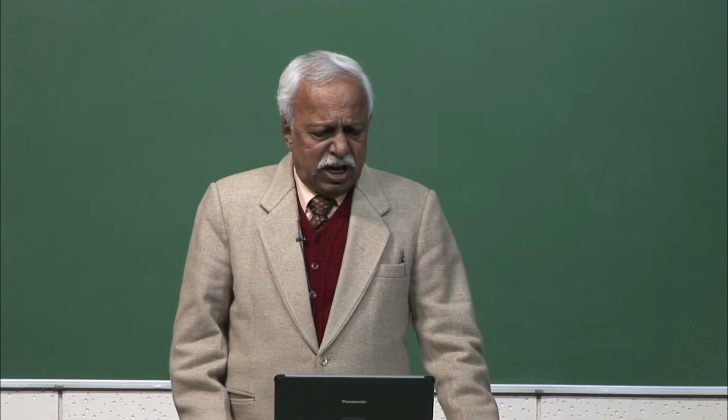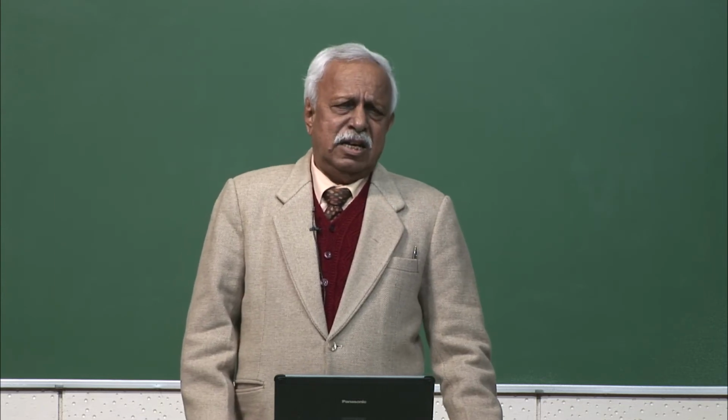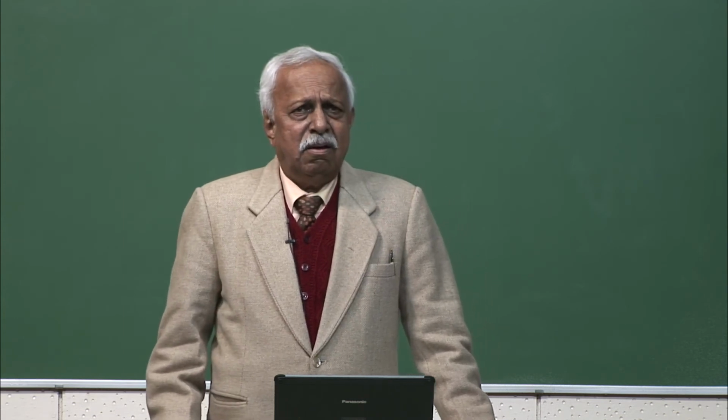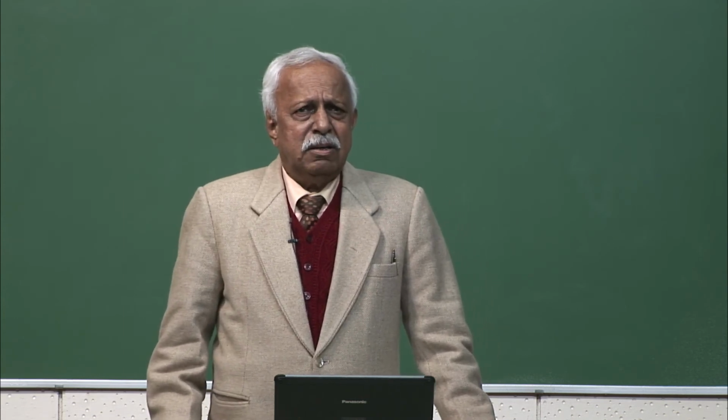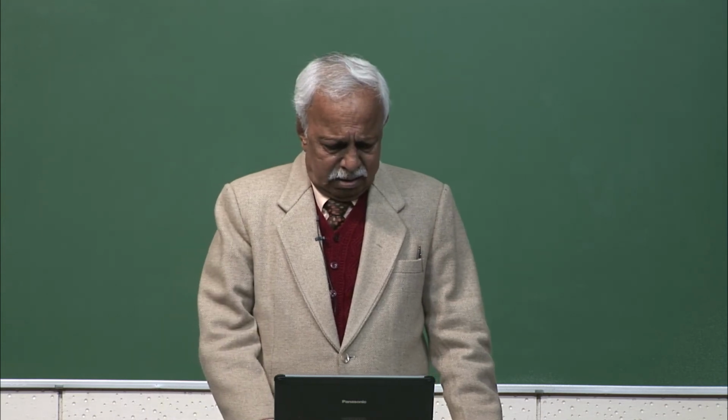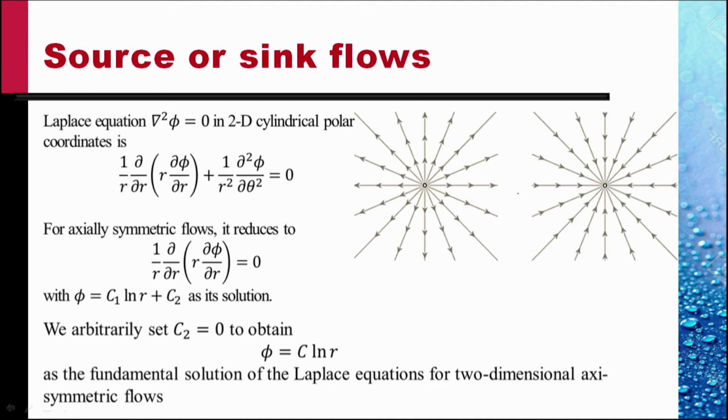So we can set C2 as 0, and then the velocity potential is constant times ln r. This is the fundamental solution of Laplace equation for 2-dimensional axisymmetric flow.